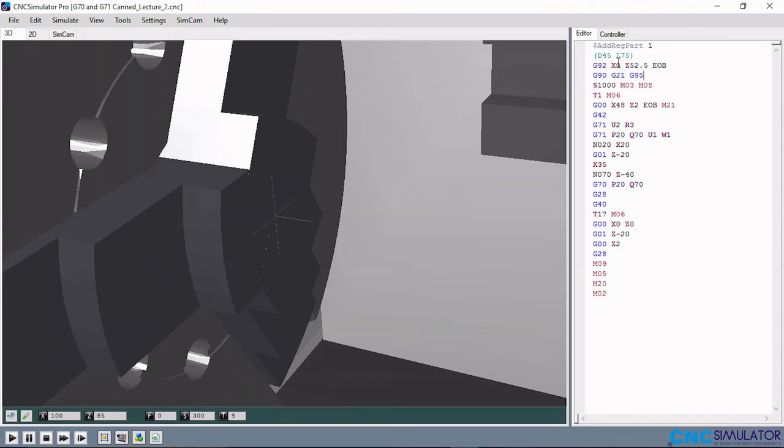What has been done here is to put in G92 X0, meaning that this cursor will be at the center of the workpiece, because X0 is where the diameter of the workpiece is 0, and that will be the center of the shaft, because lathes only deal with cylindrical shaft workpieces. So X0 makes it at the center, because the x-axis of the lathe is the diameter of the workpiece.